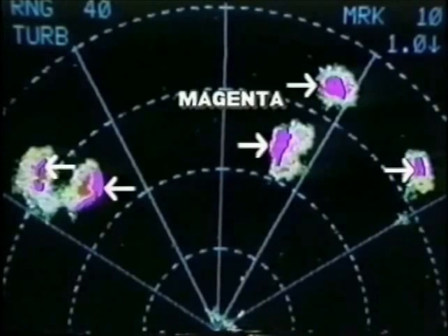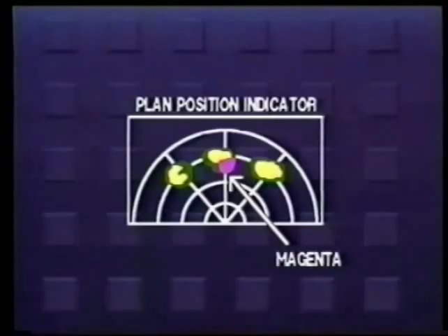Manual gain control can also be used to help evaluate range cells for the presence of turbulence. The turb display is unaffected by manual gain. By reducing the gain, and therefore reducing the strength of the displayed range signal, any areas of turbulence will be dramatically highlighted. This tool can be especially useful on EFIS displays which do not provide the magenta color.